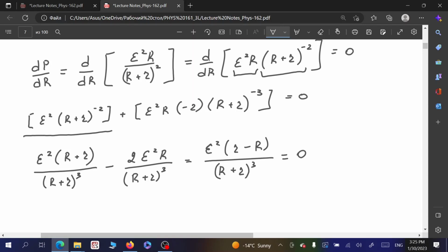So if electromotive force and internal resistance are given, then the value of the load resistor, its magnitude, will be necessary to set equal to the internal resistance of the battery in order to dissipate maximum electric energy over this load resistor.